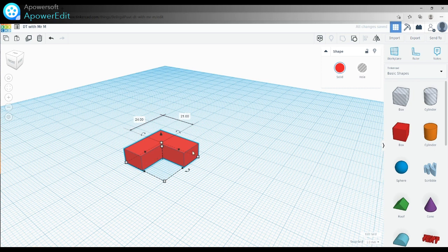and now that I've got that selected, I can go to my mirror tool, and again you'll see a series of sort of arrows on here that we can then use, and the orange preview when we hover over them. So as I click on those arrows, you can see my shape flips or mirrors.